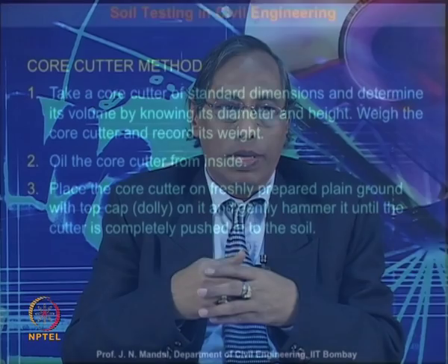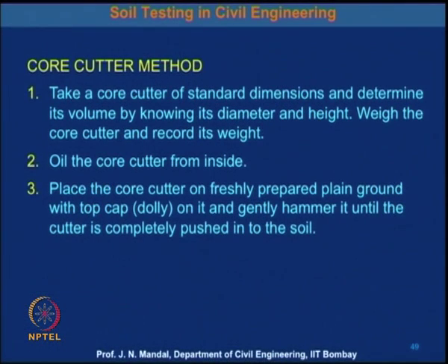So, there is another method also which you call the core cutter method. Take a core cutter of standard dimension and determine the volume by knowing its diameter and height, and weigh the core cutter and record the weight.